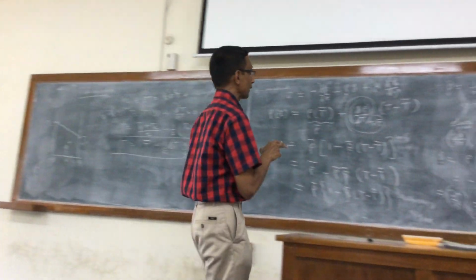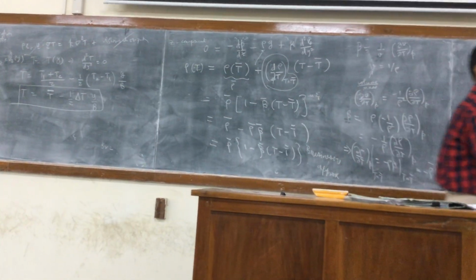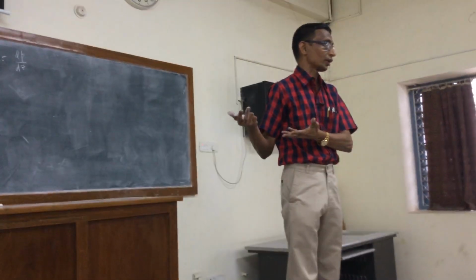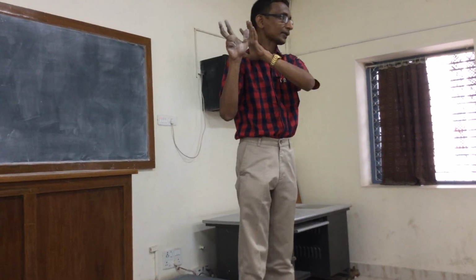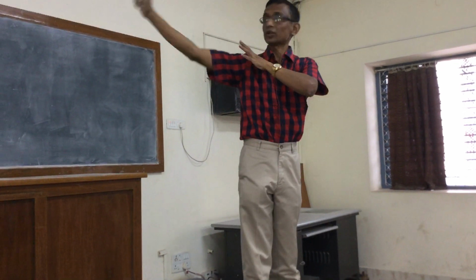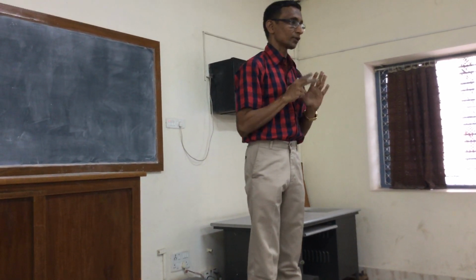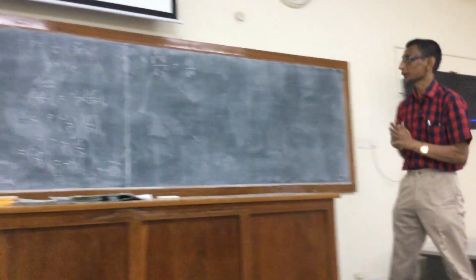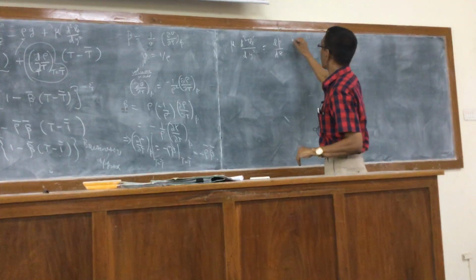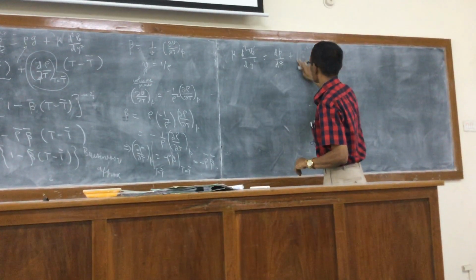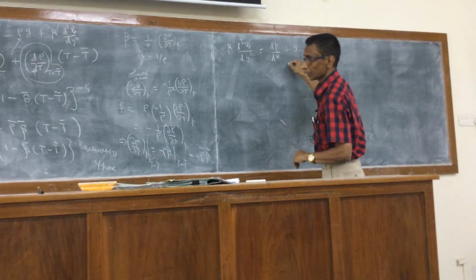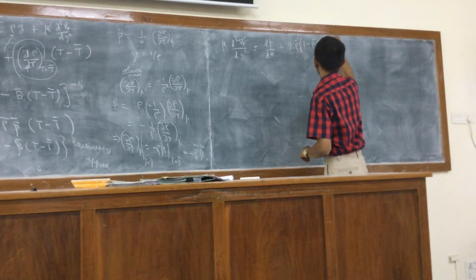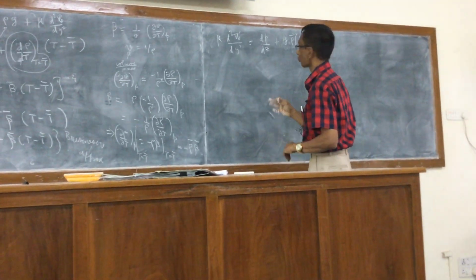But you just accept it as it is, and then proceed, because then the pressure also has to be a function of flow and temperature for a compressible fluid. So it seems like selectively it is being applied there for the density. The rest of the thing you just assume that the fluid is behaving like an incompressible fluid. Right? So plus rho g, and so here is where I get g times rho bar times 1 minus beta bar times t minus t bar. This is what we have.